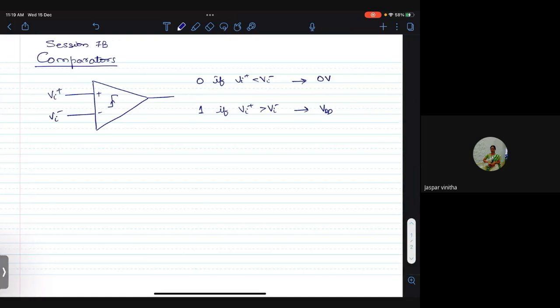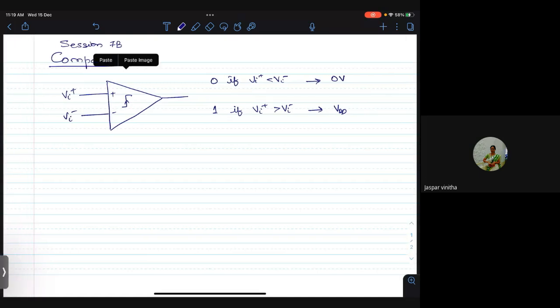So how can we design such a circuit which gives you a digital output for a continuous or analog input? One way would be, of course, to use an amplifier which has a very high gain, like what we have seen in the previous session, the op amp as a comparator. If the gain is really very high, then for a very small input your output will be saturated. But that is not always practical, and getting very high gain by using multi-stage amplifiers also implies that your latency will increase between the input and the output.